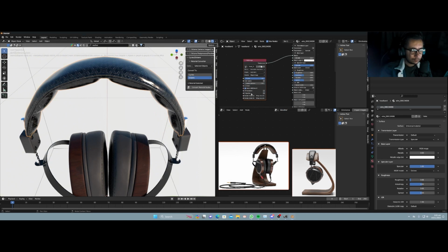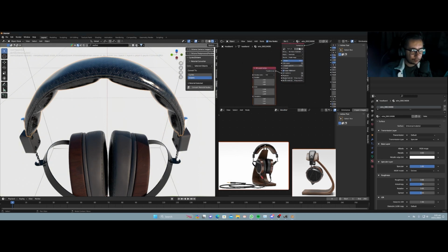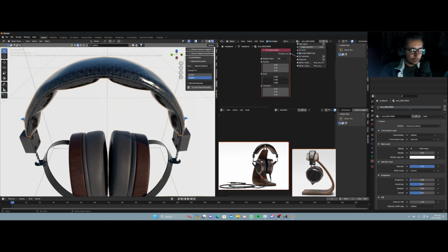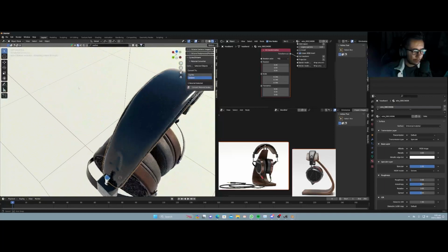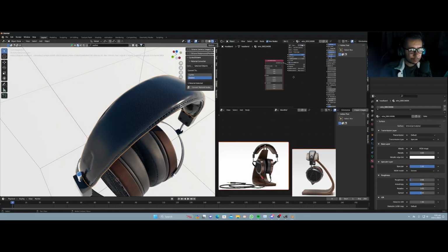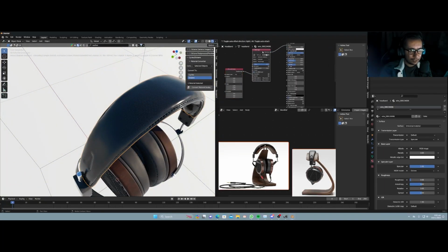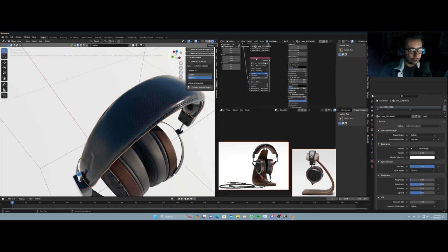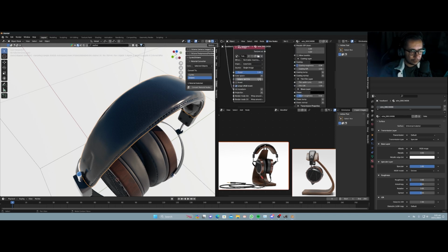Fabric. And I'll add a UV transform over here. Get the scale and scale it down. Somewhere around there. Now I'm going to be taking this, Control Shift D to duplicate it while still connected to the UV transform, and set the gamma for this one to 1.